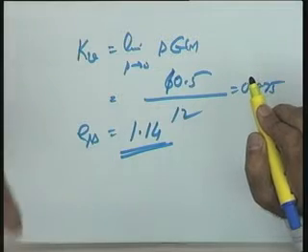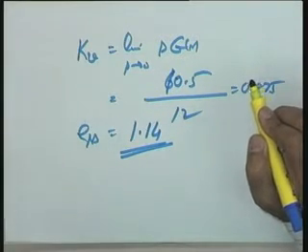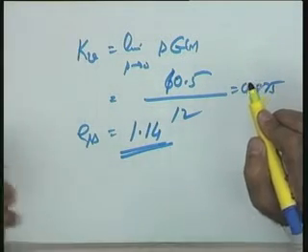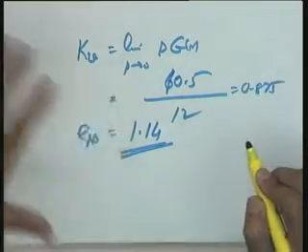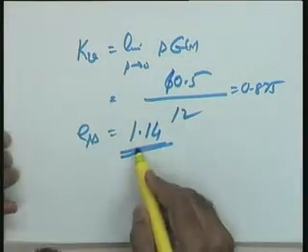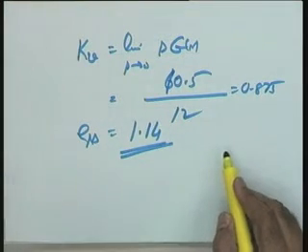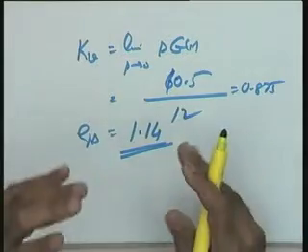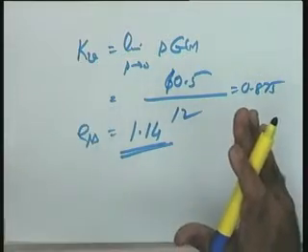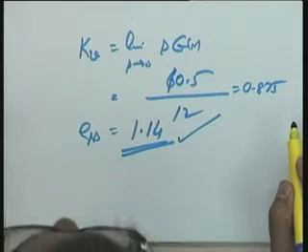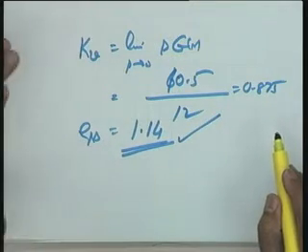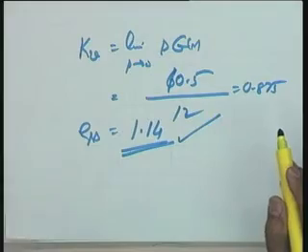Do convert it into degrees and see that your user is not going to accept such a design. You see, units also must be kept in mind. It is a position servo system we have thought of, and this 1.14 is in radians. In degrees it is too much a value, and therefore the steady state accuracy is not acceptable. So, though you might have convinced the user in terms of settling time, he is not going to be convinced as far as steady state accuracy is concerned, and hence I find that mere gain adjustment unfortunately has not satisfied the requirements. Okay? Now, please see what are your requirements, what do you want?